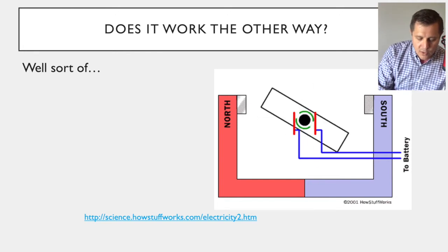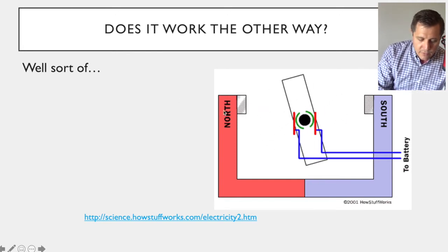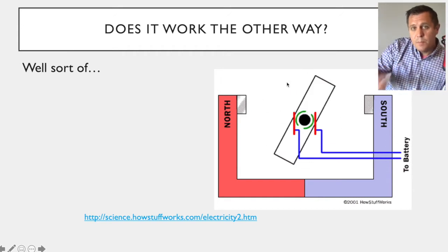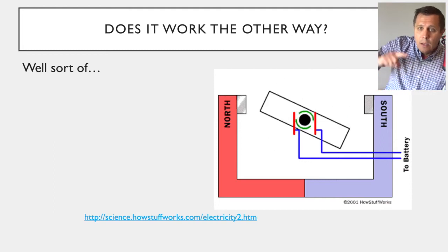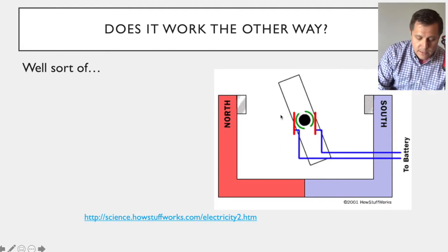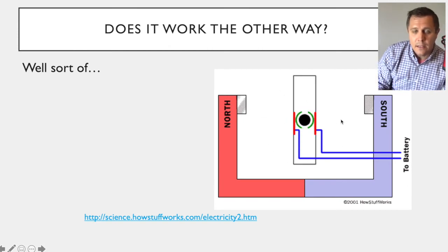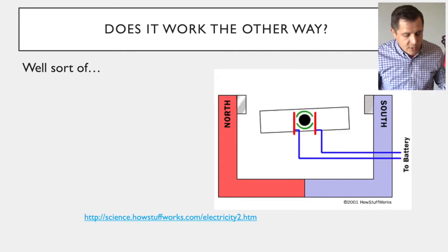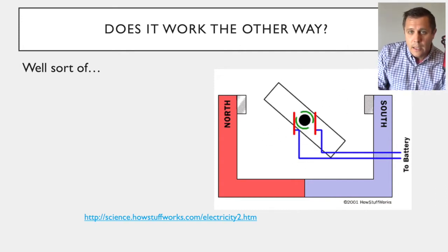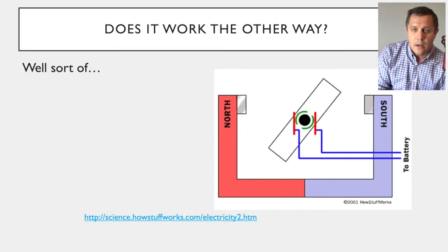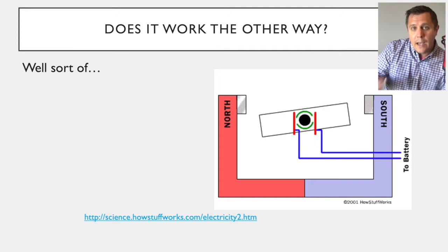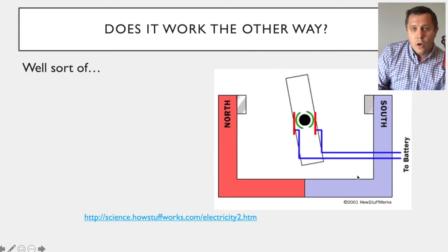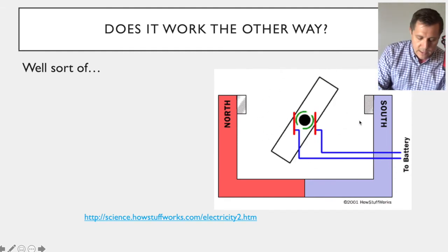Okay? Because if you think about those magnetic fields going on, from the solid state magnet going back and forth, if I spin those wires and those coils, it will constantly cross the magnetic field lines, and I can continuously add electric current onto the wire. And this is how we get electricity. All power supplies that we get, except for solar, is this idea. We are using some type of energy to spin electric wires so that they keep crossing magnetic fields and we can get current going out to a battery as it shows here or wherever.